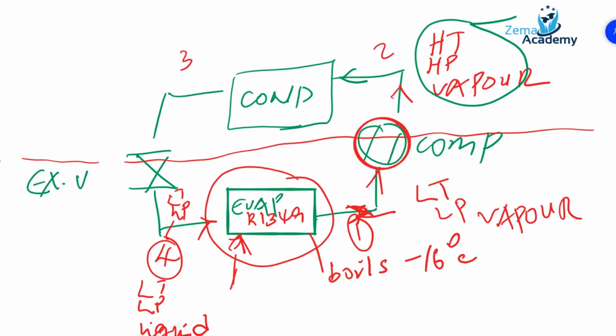By passing it through the condenser, you're rejecting, you're sinking that heat. Here you will have a secondary circuit to remove the heat from the condenser. Again, we will look at whether you're using air or water to remove the heat from the condenser, and that's how a condenser is classified: as either an air-cooled or water-cooled condenser.